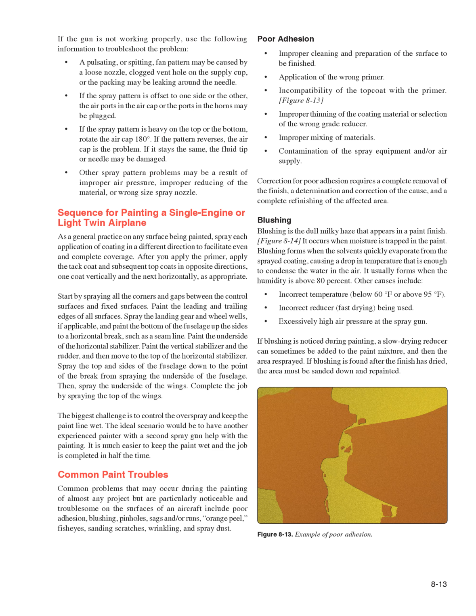A pulsating, or spitting, fan pattern may be caused by a loose nozzle, clogged vent hole on the supply cup, or the packing may be leaking around the needle. If the spray pattern is offset to one side or the other, the air ports in the air cap or the ports in the horns may be plugged.